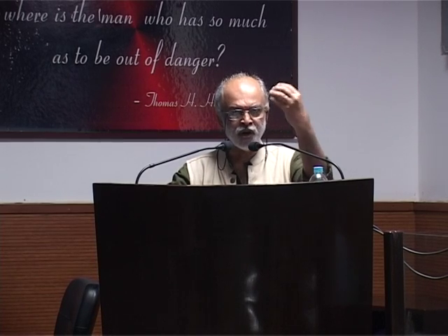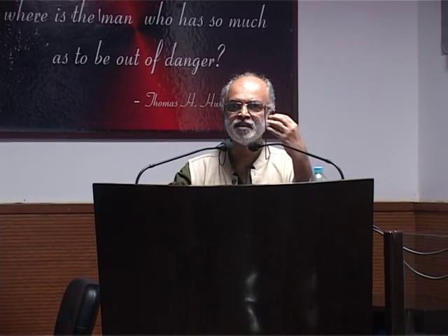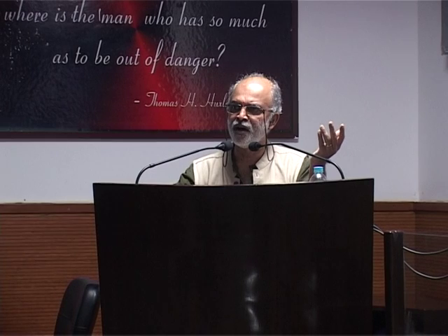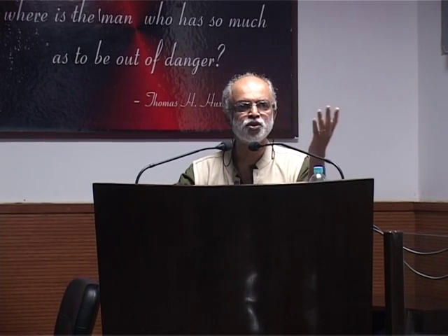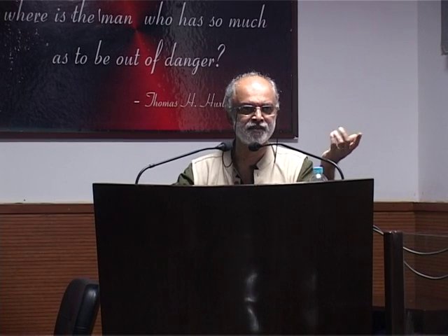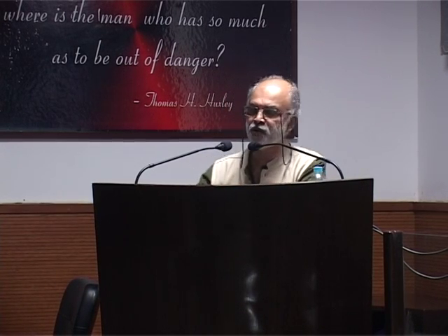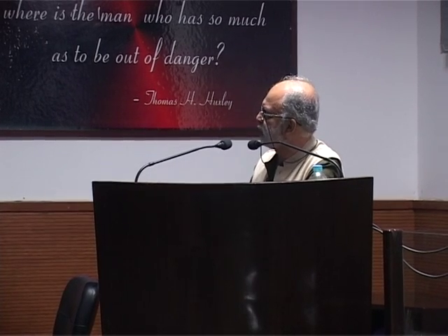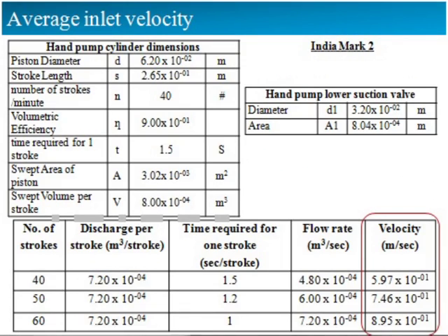If we can have a control over this cavitation phenomenon, then it is indeed possible for you to manipulate it and bring out the cavitationally induced transformation much more efficiently, much more effectively. And we have used this particular phenomenon for disinfection of potable water. And again, these are all the details, how you start, you analyze the piston diameter, all the geometry, the stroke length, the number of strokes which you can get. Typically when you are doing a vigorous pumping, you are doing about 40 to 50 strokes per minute when you are pumping water. As long as I get those kinds of flow rates, cavitation does occur.